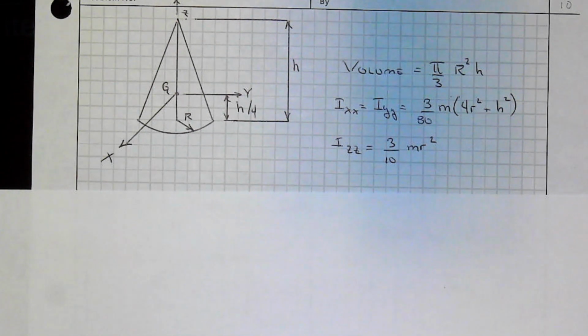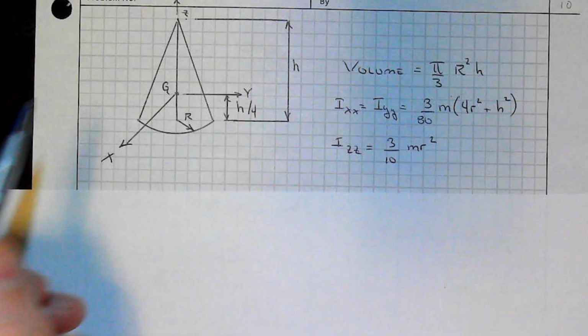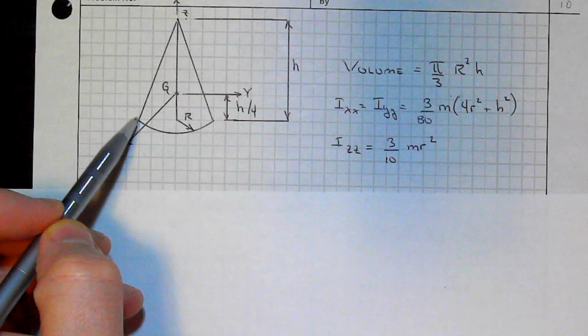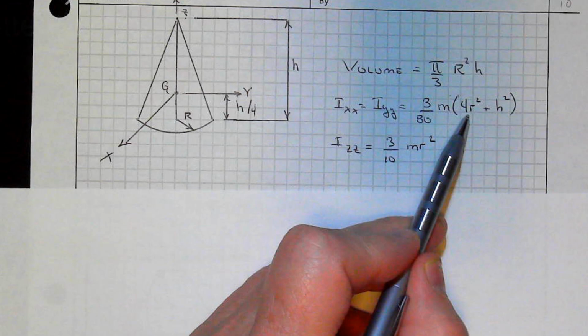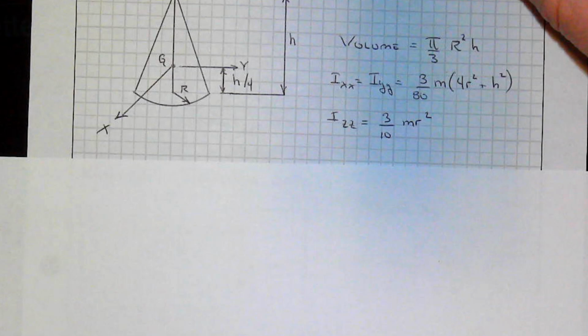So, time to compute mass moment of inertia for composite parts. I'm going to go into my tables again and give you a little information. This is what would be called a right cone, because its center comes perpendicular off of the base. At the base we have some radius r, and this goes all the way around. Here's G, so the centroid of the cone, or center of mass as it were, is at h over 4.